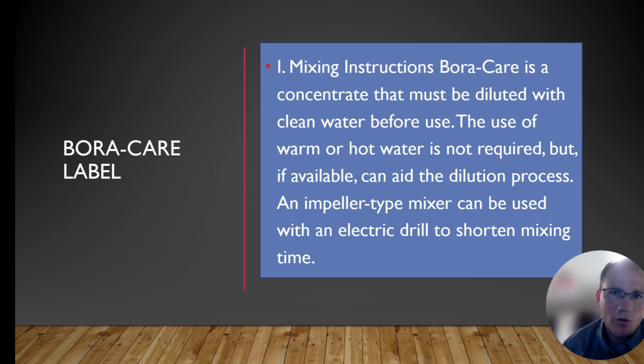I can tell you, if you've ever used Boracare, it's a thick gelatin type of substance. I mean, if it's cold in the wintertime where you're at, it can be really, really tough to get this product to mix. You're going to spend a lot of time. So I just wanted to let you know, just like the label says, that warm or hot water is great. I'm sure most of you won't have something like that on site. So keep in mind, you're probably going to be using regular cool water, or obviously even some cooler cold water if it's really cold out.